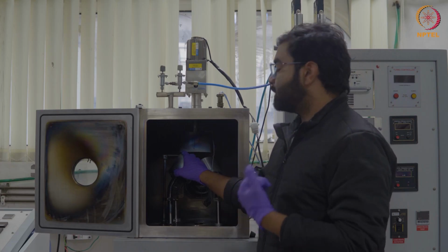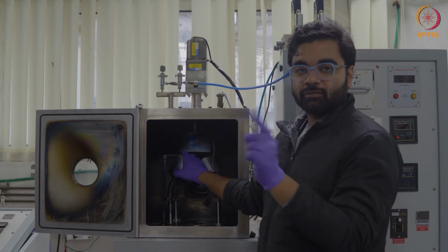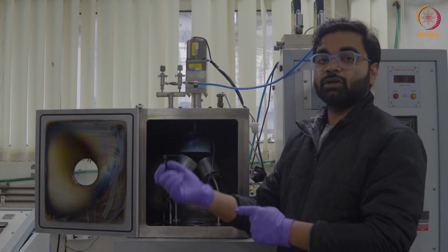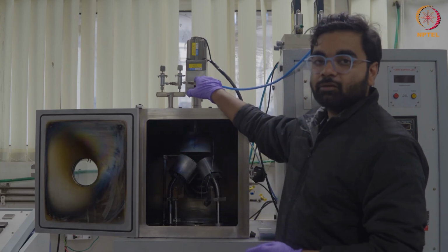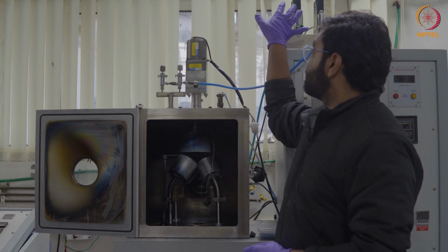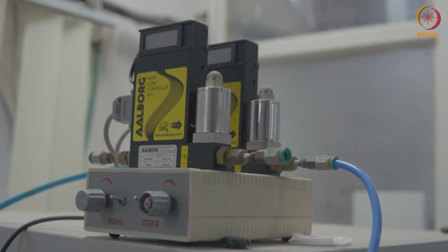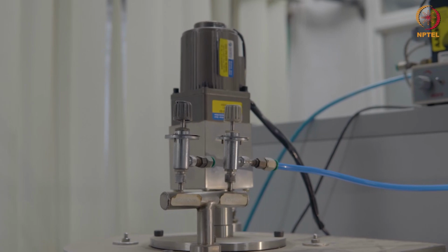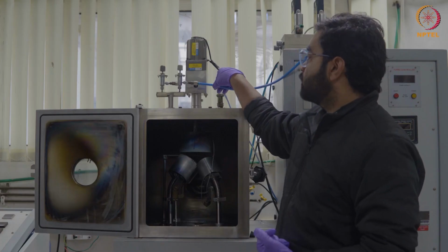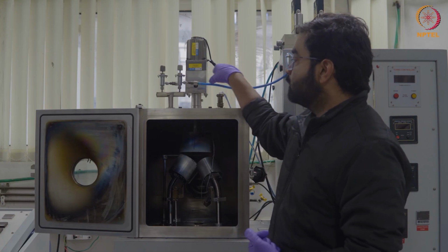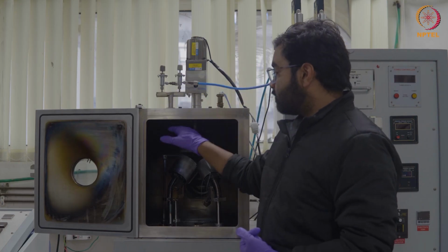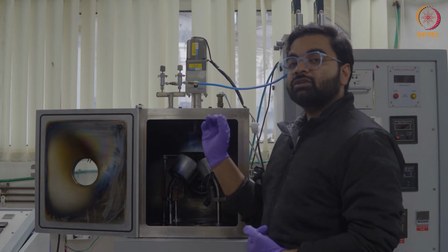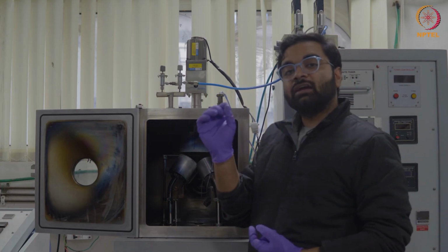What do we have to do in order for the material to come out from the surface? As I told you, the case of the mango tree: you have to throw a stone at the mango tree for the momentum to transfer. So in this case, we purge argon gas. Now the argon gas is connected through this MFC. MFC is mass flow controller. It allows the argon in a controlled manner, whatever control we want, so how many cubic centimeters of argon we need to feed. We can control it, and as the argon flows from here, this chamber will have some amount of argon. Now this argon will act as those stones.